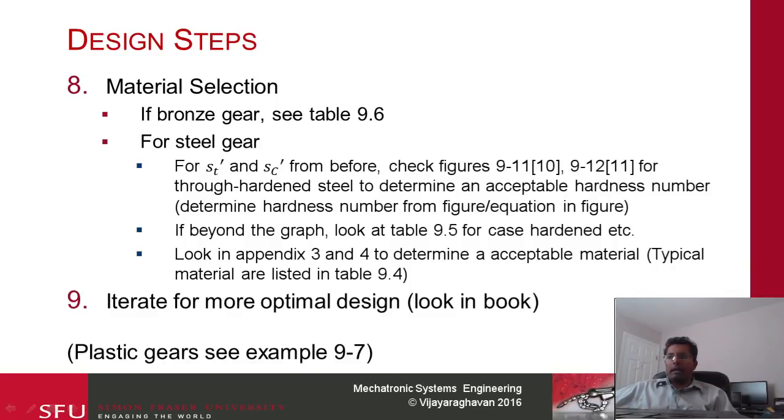So once we do that, we would have the final gear, and then we can say, okay, this is the gear size I want, this is the diametral pitch. The person actually manufacturing, so you can look up the videos on gear manufacturing, would either hob or cut the gear to our required specification. So this concludes our introduction to gears. In the next video, we'll look at actually solving an example using a sample problem, and then we'll be referring to Machine Elements in Mechanical Design, 5th edition by Robert Mott. Thank you.